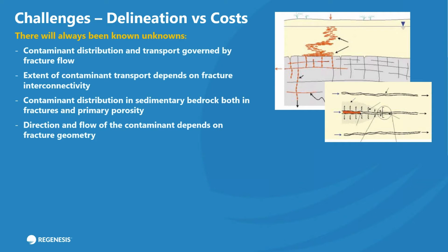And this is something that is going to be crucial to, one, understand, but also to communicate to all stakeholders, be that remediation practitioners or the liability holder for the site. Because while in the initial phases of remediation, you may see a significant drop in contaminant levels from remediating contaminant mass in the fractures, you have got this secondary source of contamination in the rock matrix.